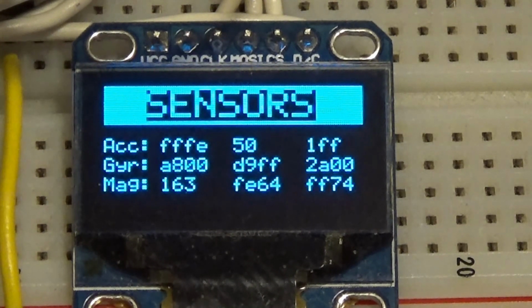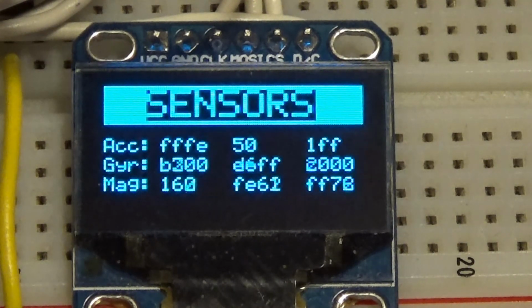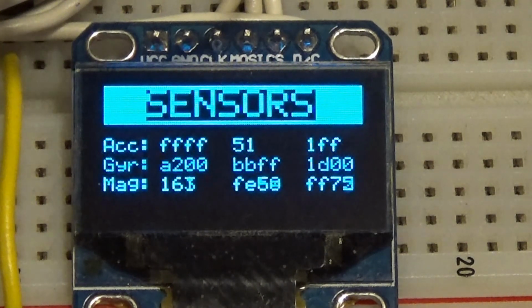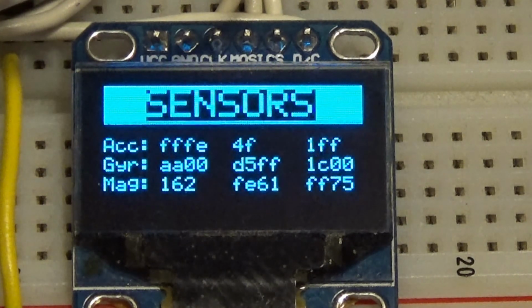It is way faster than the I2C bus. If you've got peripherals that require a lot of data to be transferred back and forth, this is the way to go, because it's so much quicker. I'm doing it at 8 megahertz here, which is the fastest that the microcontroller can do. But I've worked with other microcontrollers, and I'm not sure what this display is rated at, but other peripherals can take data at 20, 30 megahertz, and so it doesn't take long to transfer a whole bunch of data to something, or read data from some device as well.